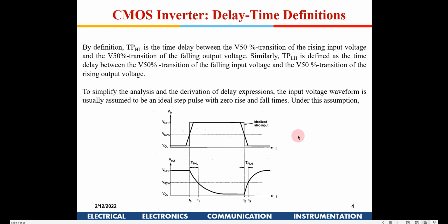So in that way, let's say an inverter is driving another inverter, the load capacitance would be, if the NMOS source is grounded, something like the gate to body and the gate to source capacitance. Is this correct? Yeah. I'll get to those slides, they are coming up.